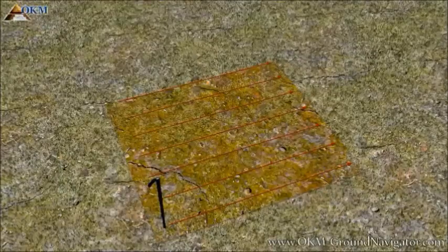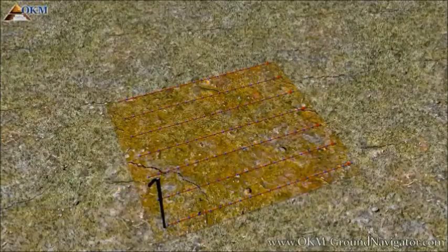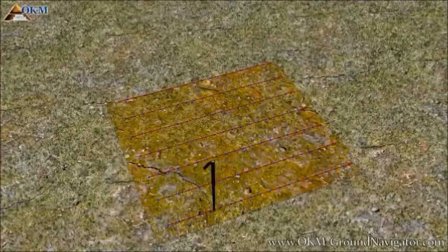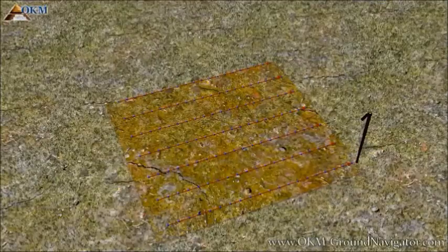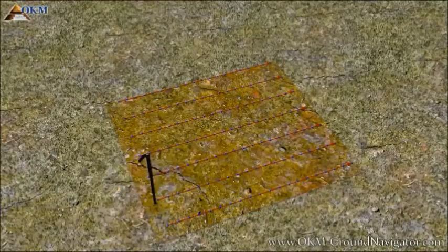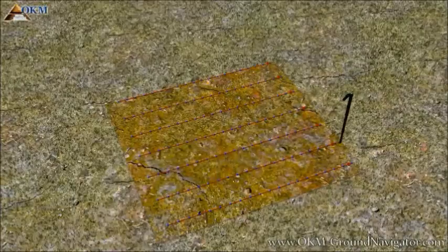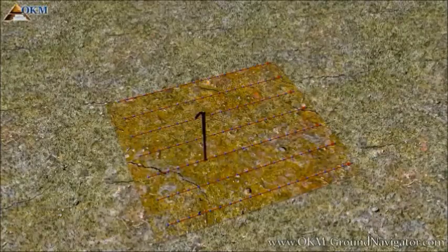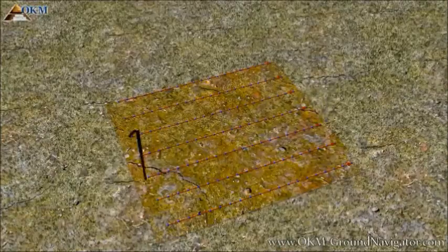You can easily see that this is the parallel mode, since all arrows are pointing in the same direction. Each of the blue dots represents a scan value that can be measured manually or automatically. Now you start walking the first path to collect measure values. If the first line has been finished, you come back without measuring, and then you step to the left to scan the next path. This procedure is repeated for all scanning paths.